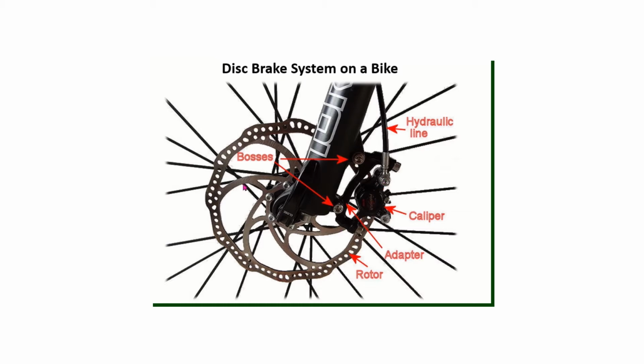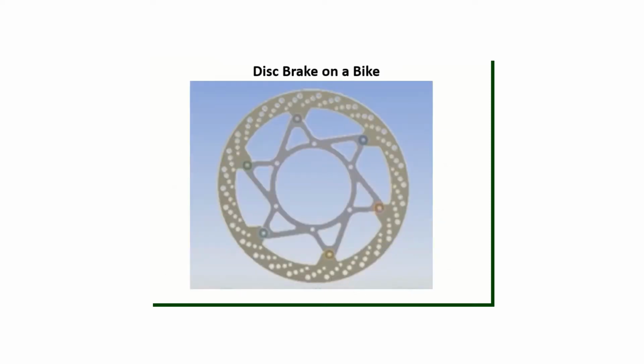We've been given a CAD model of a disc brake system in an IGES format. We will import this file into SpaceClaim and perform a geometry check. When importing CAD files into finite element models, the geometry can contain a lot of detail that isn't needed and really slows the meshing and solution processes down. These details are removed through a process known as defeaturing. We will look at some of the defeaturing tools available in SpaceClaim.